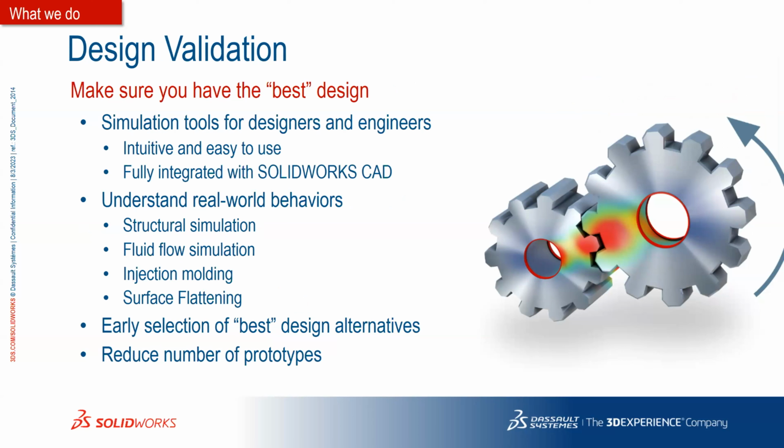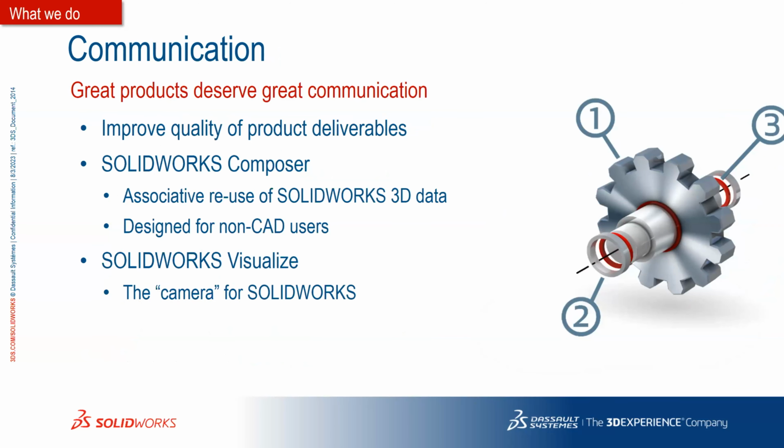If I design something and I want to test its integrity or its strength, where I want to utilize this is: is a specific load going to work on a specific part? I can then use SolidWorks Simulation, where I can test real-life scenarios on my designs. So it ranges from structural simulation, fluid simulation, injection molding. So if I'm in the injection molding environment or plastics environment, surfacing, I can test all that as well.